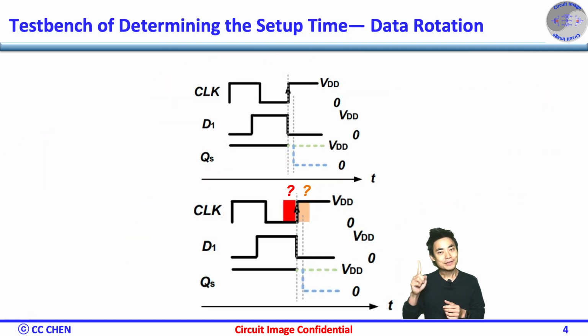Right, the first thing you need to do is to understand your flip-flops well in the setup time requirements. Remember, at your clock rising edge, the data transition before the clock rising edge must be earlier than the setup time window. Otherwise, metastability occurs. Now, we need to know what the setup time is here by assuming the flip-flop is a black box. What should you do?